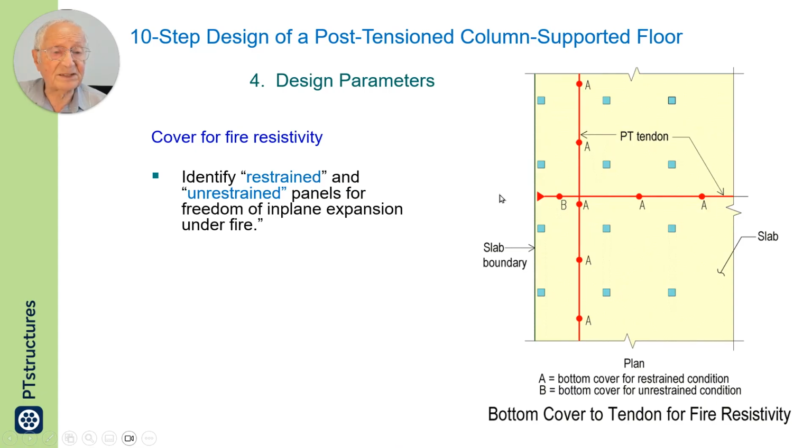Unrestrained means it can expand. For fire resistivity and its requirement, we look here and say this exterior panel, if not attached to a beam or wall, can expand out in case of fire, heat of fire.